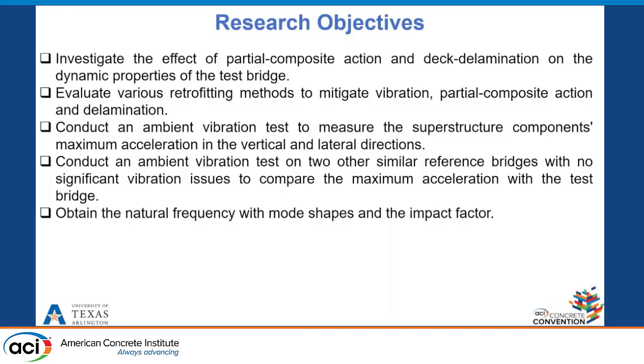And number 3, obtain the natural frequency and mode shapes of the test bridge by conducting dynamic tests. Number 4, model a representative girder with an effective deck width of the test bridge in Abaqus CAE and calibrate it using the load test data. And finally, number 5, apply practical and cost-effective stiffening methods on the calibrated model to mitigate the vibration.